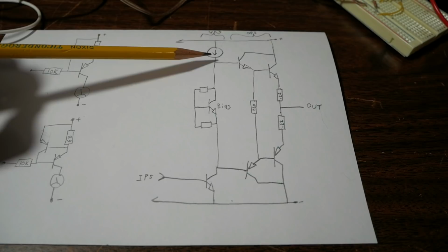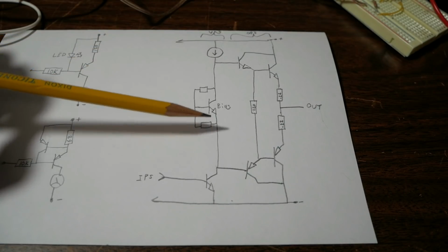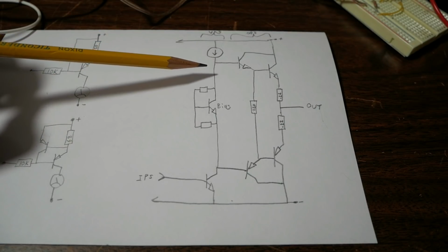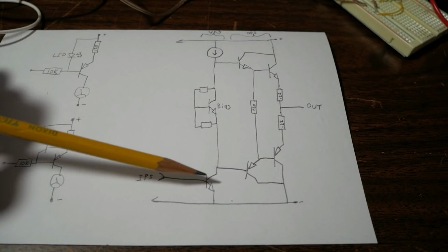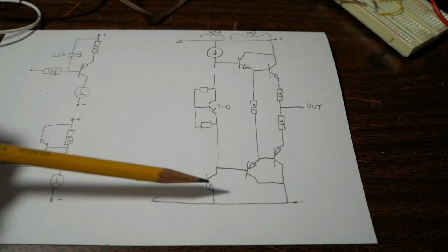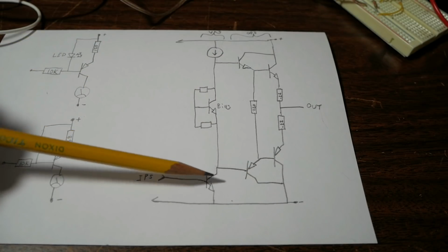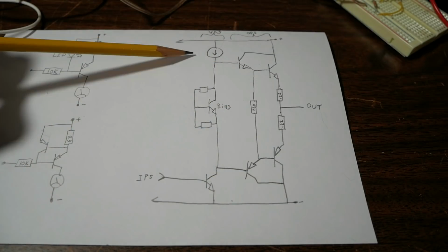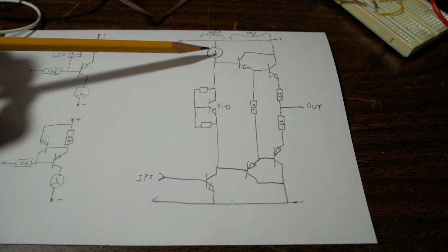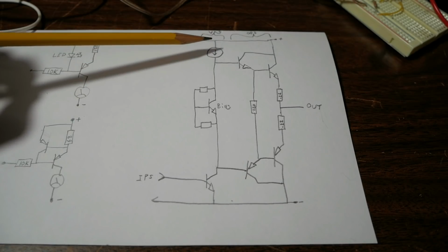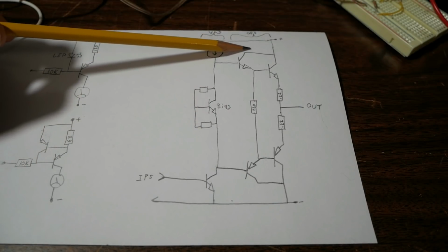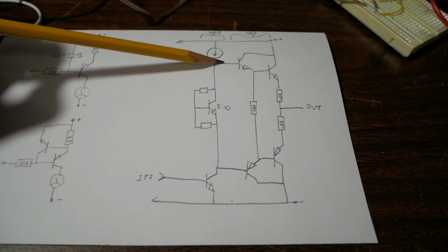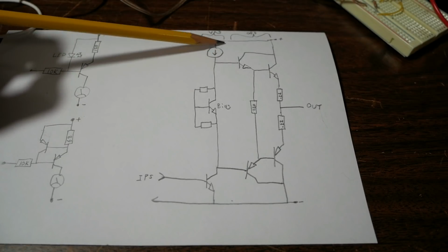Another property of the constant current source is infinite impedance. Well, in the real world it's not going to be infinite, but it's pretty high impedance. So it doesn't impose a very heavy load on this transistor here. In other words, it allows that voltage to swing freely. And a third property of the constant current source in the VAS stage is it has to have a low dropout voltage. Remember, when this voltage is swinging towards this rail here, the voltage drop at this point to the rail is going to be very low.